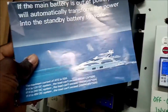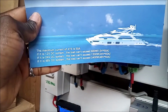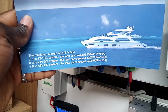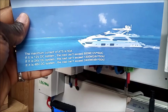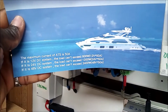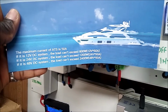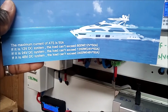You will receive this leaflet once you purchase it and receive your package. As you can see, it tells you that if you're using a 12-volt system, the load cannot exceed 600 watts, and if you're using a 24-volt system, it cannot exceed 1,200 watts. The way they reach that calculation is 24 volts times 50 amps.